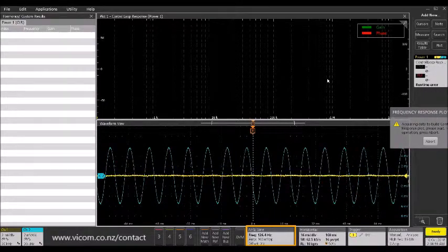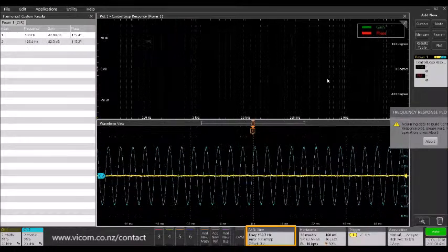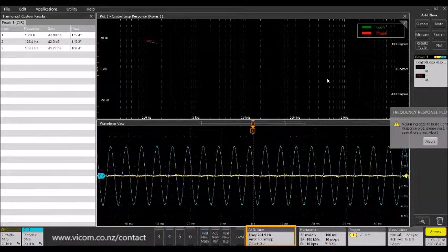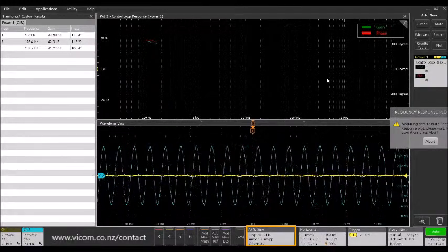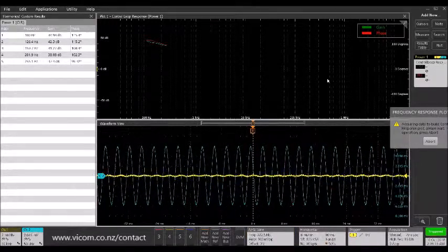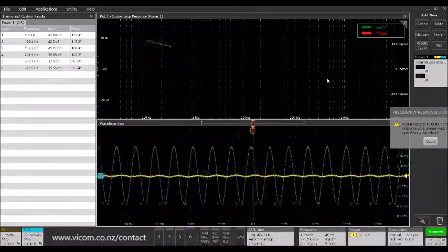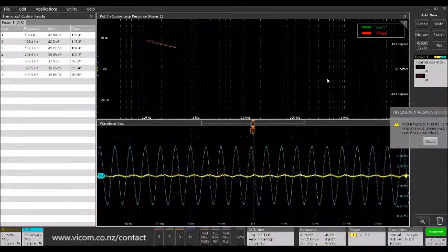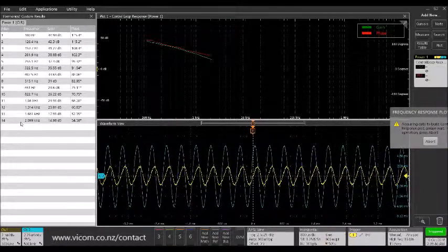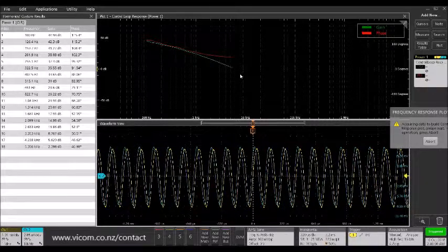And once you press the preset, the software automatically enables the AFG, as you can see at the bottom there, and the test is started with the frequency being swept from the start to stop frequency at the desired amplitude. As you can see, the plot is frequency versus gain on one side and frequency versus phase on the other side. So it is a three-way plot which is rendered as the input and output are measured, and the phase and gain plots are taken through.